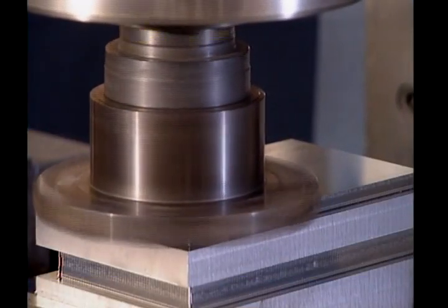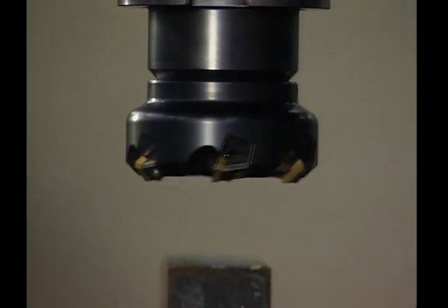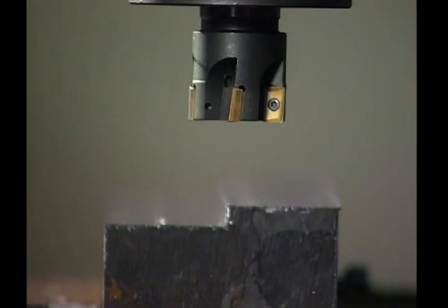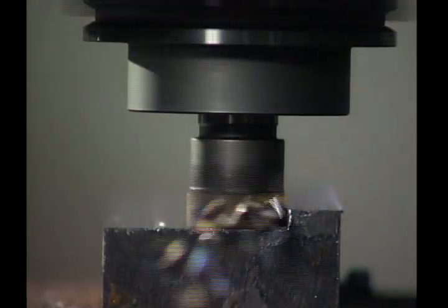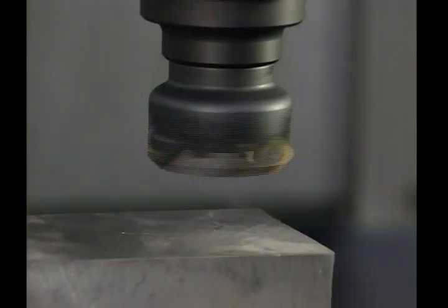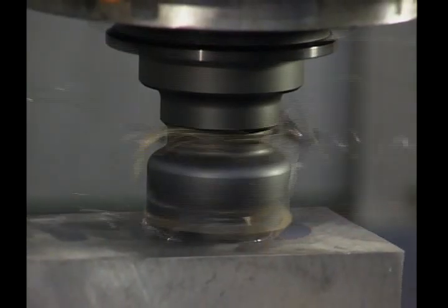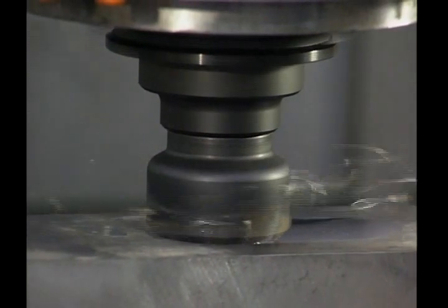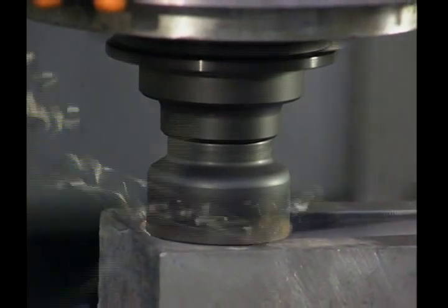The milled surface results from the combined action of cutting edges located on the periphery and face of the cutter. The flat milled surface has no relation to the contour of the individual teeth, except when milling a shoulder. Not all face mills are used for large, straight cuts. Some small diameter face mills are used to ramp into a surface, then plunge to a depth, and interpolate outwards to mill a large pocket more efficiently than an end mill could.